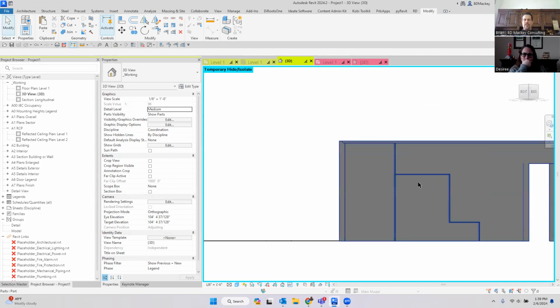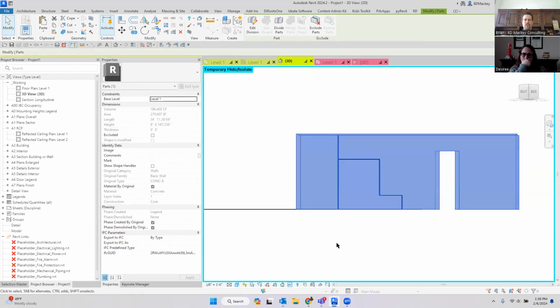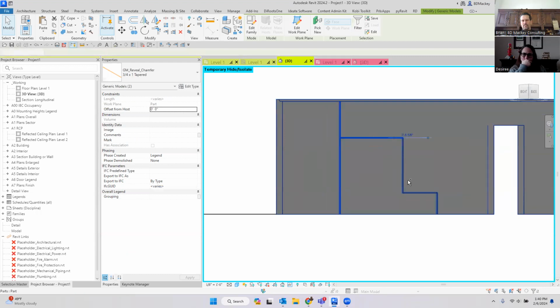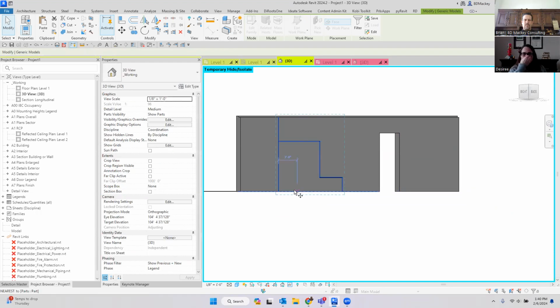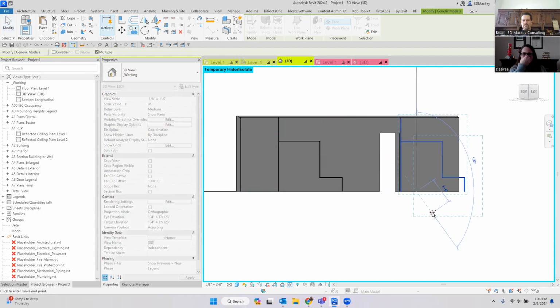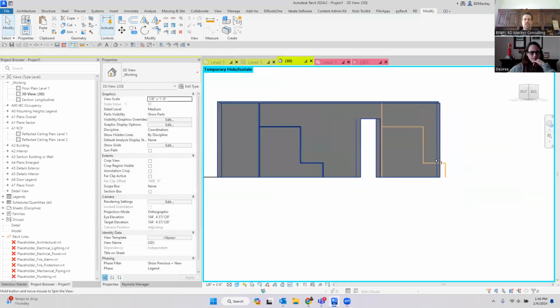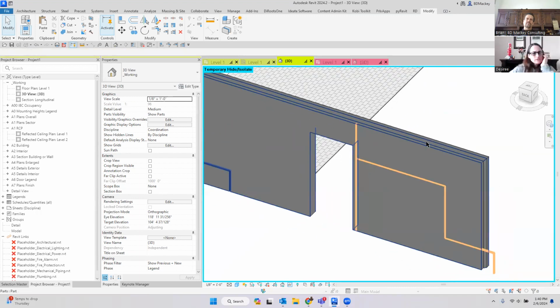Right, so I'm not a big fan of the actual reveal command. And then if you wanted this a multitude of times again, then you can grab those and copy it onto the same wall. Probably not long enough to copy it over there, but as long as it's on the same host object, there you go. You do have to run the cut tool each time, which is kind of frustrating, but you get the point. So hopefully that makes sense, what you're talking about.